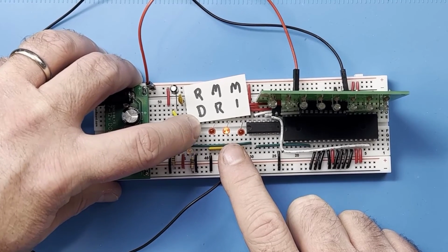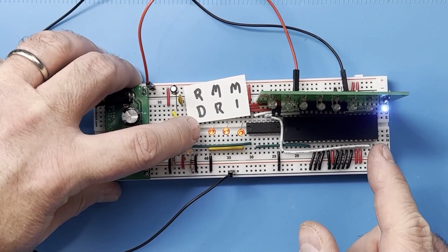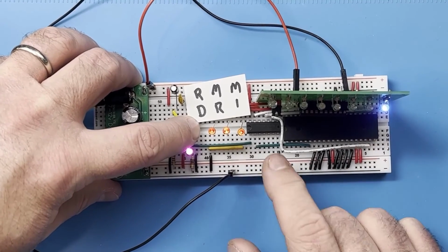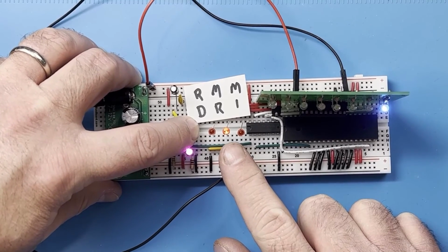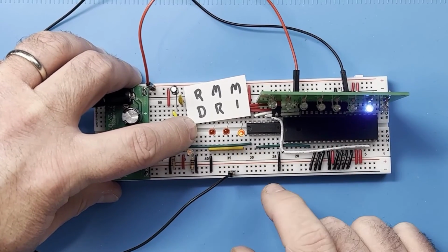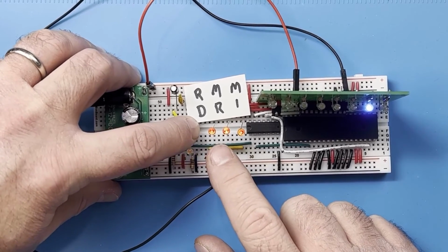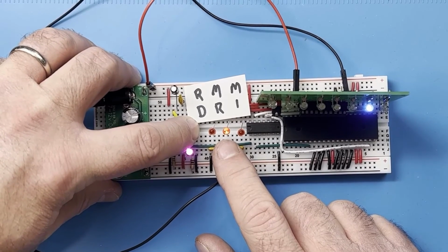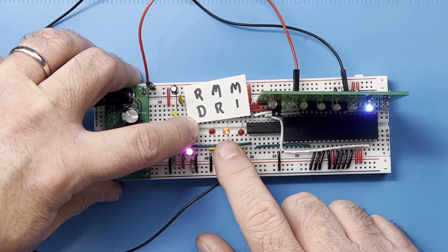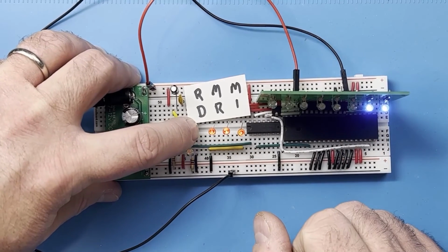And then when I push it back down, the MR goes out, and we've got our first light lit up here. So if I keep cycling through this, and we can watch the M1, the MREQ, and there we go, we've got another one. So if I just keep going, we should be able to see the board counting in binary as we go through these steps of the T cycles.